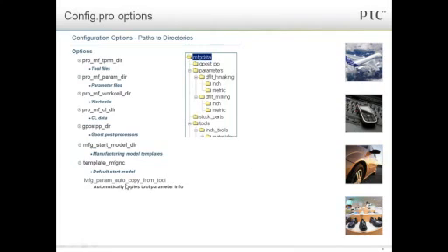Essentially it says manufacturing parameter. I want you to copy or auto copy from your tool all of the parameter information into your parameters. And the value would be set to always, or I think it's actually set to all, excuse me, it's all. And then what happens is, as long as you have your tool set up that has your parameters, it'll actually drive that information from your tool into your parameters, and you don't have to set that information